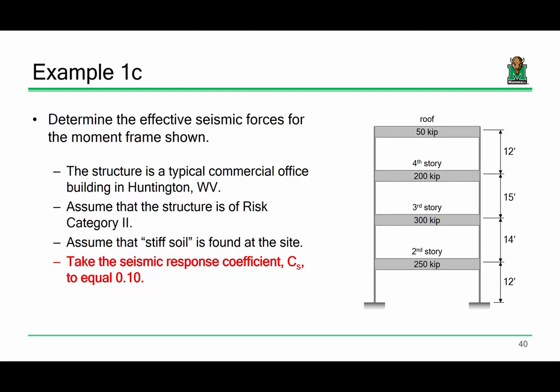Now when you're looking at seismic analysis, what you typically do is compute the weight of each story and lump that as a single load. Because think, as you're starting at the ground and working your way up, really the heavy parts of the building are the floors, the individual floors. So like right here, remember our secret weapon of structural engineering, right? Remember the samurai sword or the lightsaber if you happen to be a sci-fi fan?